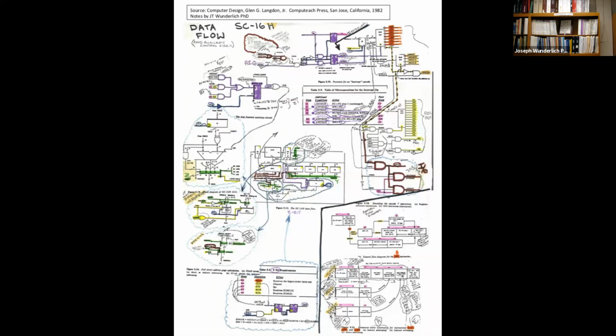Now you look to the right and you see how IO commands are handled, and also in yellow, the register reference instructions, how the signals are created for those. When it's decoded during the instruction pipeline, the first phase is fetch, then you decode, and then you create the control signals. That's what you're seeing here in circuit implementation form.